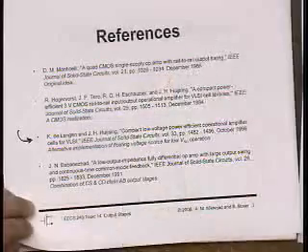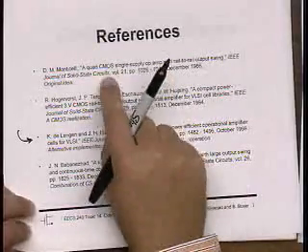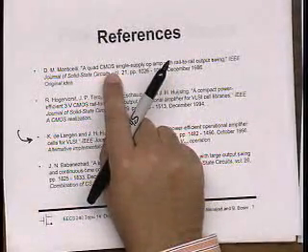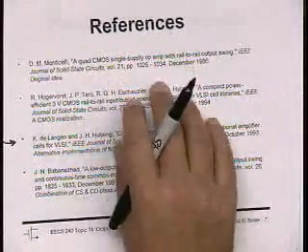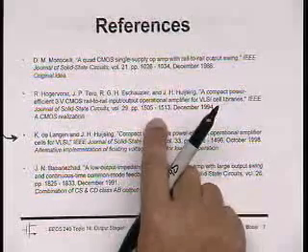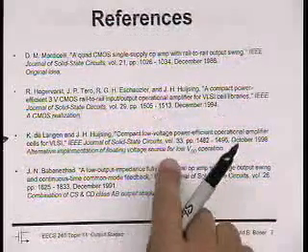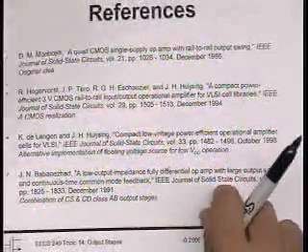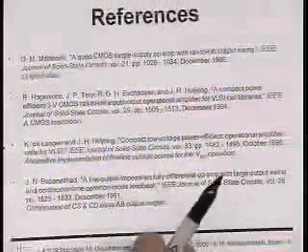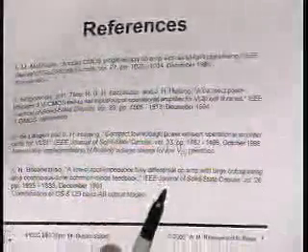But there's several output stages. This original output stage is a CMOS, single supply output stage, using bi-CMOS technology. This paper here is an all CMOS implementation. This one is an implementation with a low voltage source. And finally, this implementation uses something that we'll talk about a little bit later in the lecture.